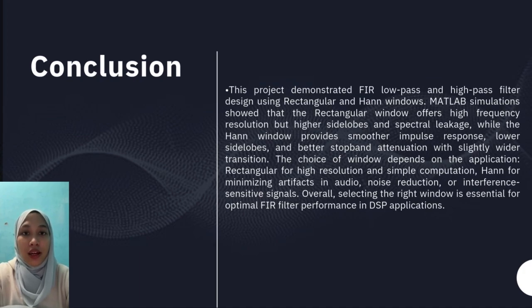The choice of a window depends on the application. Rectangular for high resolution and simple computation, Hann for minimizing artifacts in audio, noise reduction, or interference sensitive signals. Overall, selecting the right window is essential for optimal FIR filter performance in DSP applications.